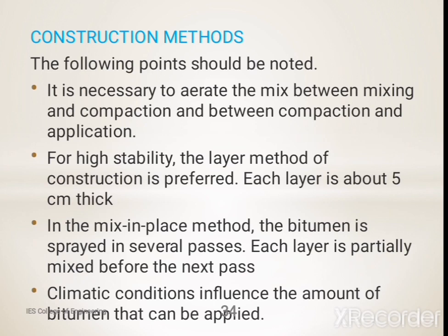The construction: it is necessary to aerate the mix between mixing and compaction and between compaction and application. For high stability, the layer method of construction is preferred. Each layer is about 5 cm thick.